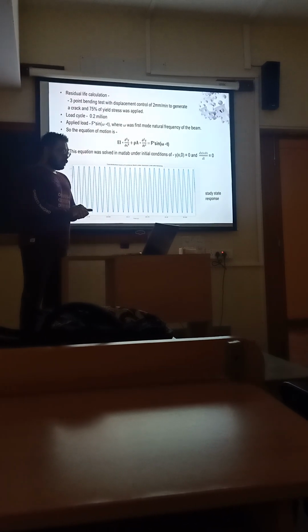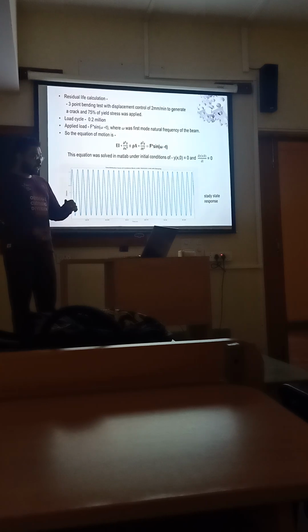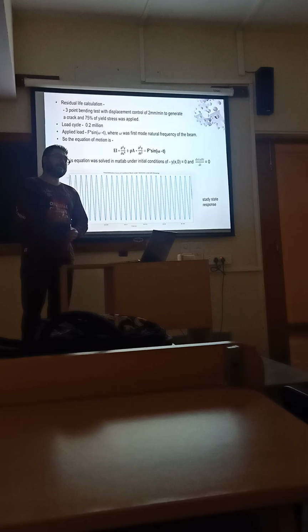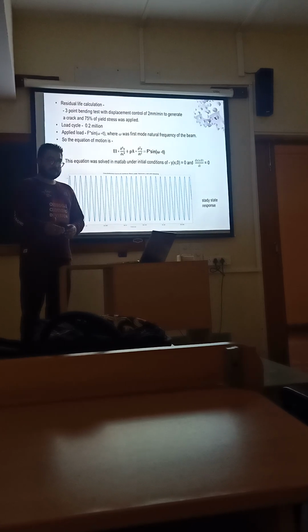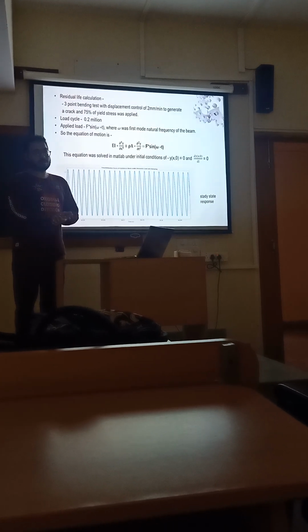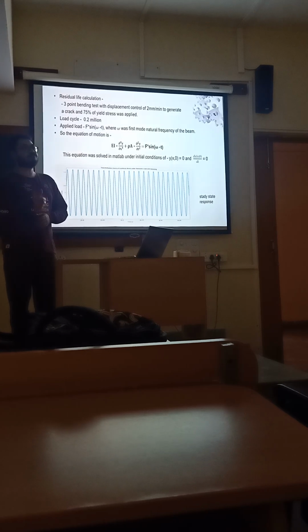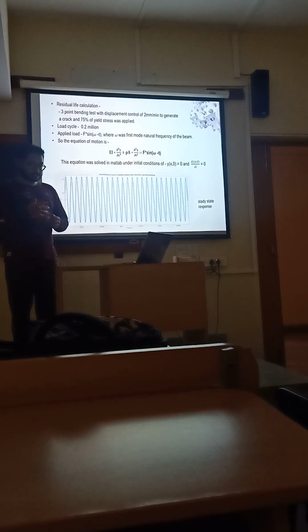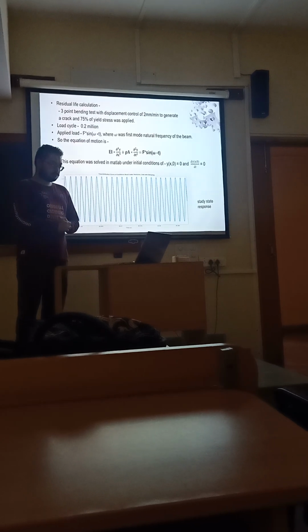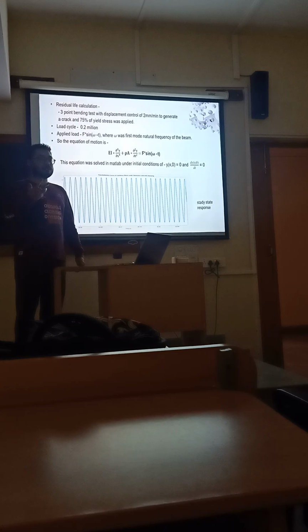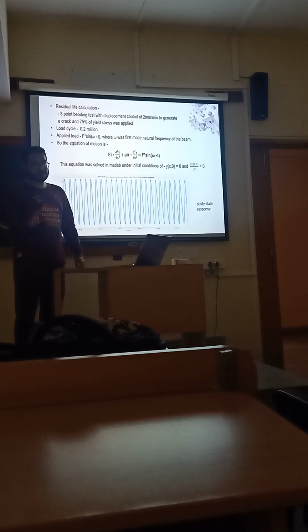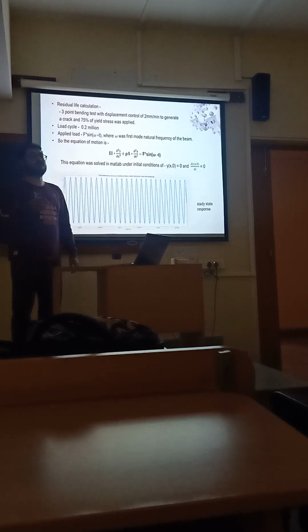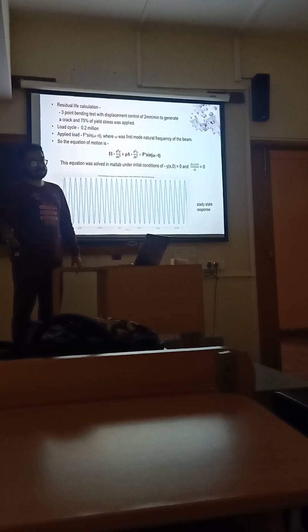For composites, since it's a composite structure, I have created a notch. After that, I created a crack with a 3-point bending load, so that the primary mode of failure becomes delamination. I did this deliberately because I should have control over the type of crack forming, because if there are multiple cracks, it will be very difficult to predict for which crack the structure is failing.